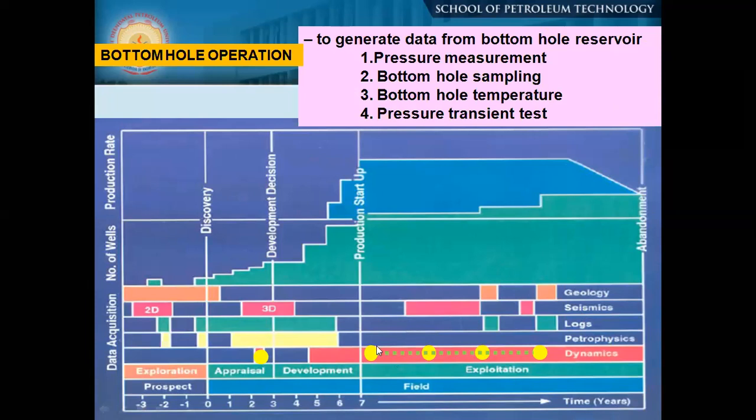These are the pieces of information put together. When we get this dynamic information, let me brief you how things happen. We start drilling a well, then go on drilling continuously, and in between we collect core plug samples as well as fluid samples by modular dynamic tester. Then we complete the well at last target depth, and case the well. Then we perforate the well.